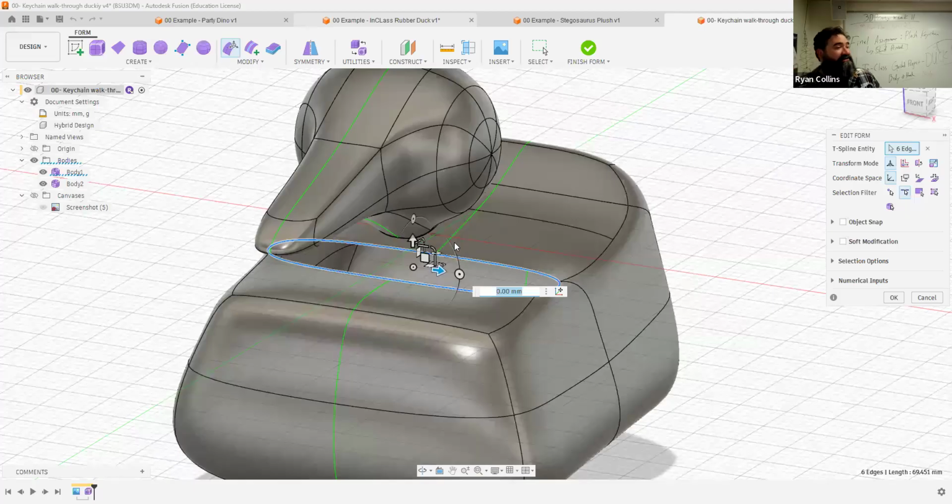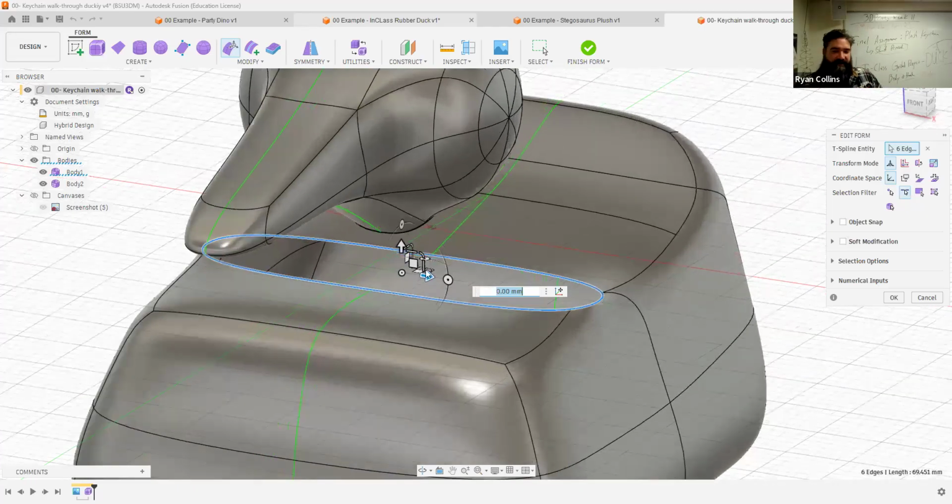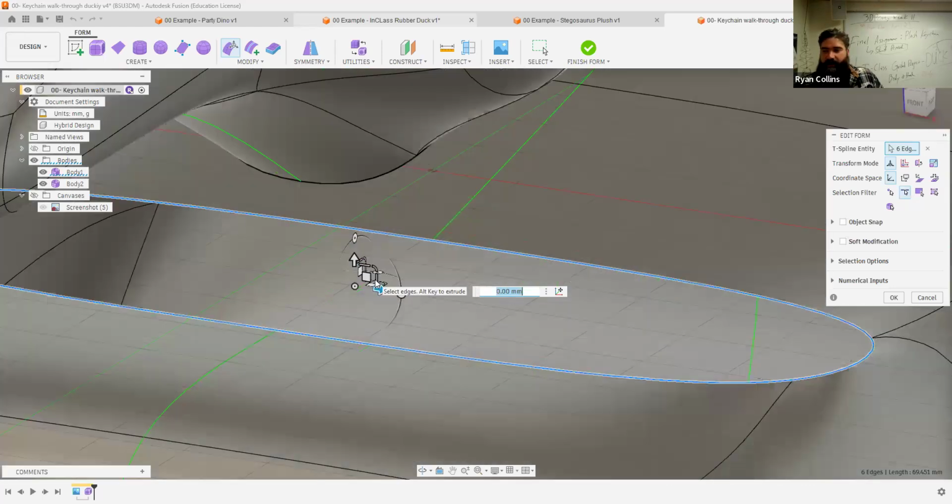And I'm going to use the scale tool because that'll just shrink everything together. However, I want to use just the one-dimensional scale. So if you zoom in, it doesn't really change the size of the tool there. But you can see just those edge lines. And let me isolate this by going to the transform thing to just scale. There we go. You don't have to do this. It just makes it easier to see what I'm doing. So remember just the lines around what are representing the planes.